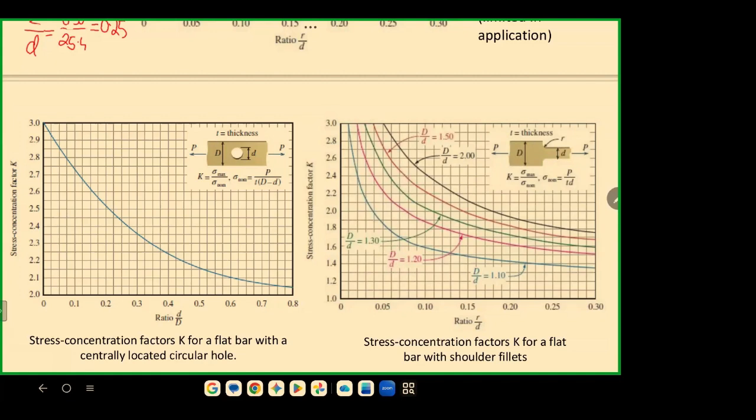Now, obviously, you can go and look for stress concentration chart manuals in the library, or published charts in other sources like standard bodies, they publish charts as well. If you can find a closer one, that's good. But let's say you can't find a closer one, or you want to have a quick estimate of the design, right? Because later on we will be doing finite element analysis anyways, right? So let's go by this chart for now, noting down that this is a limitation of our analysis.